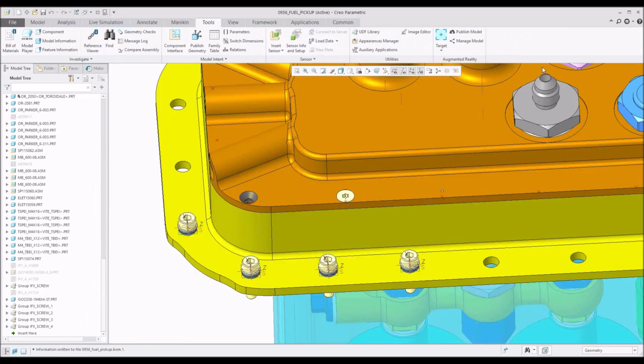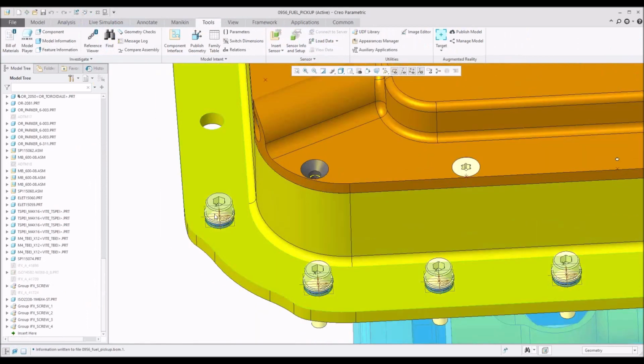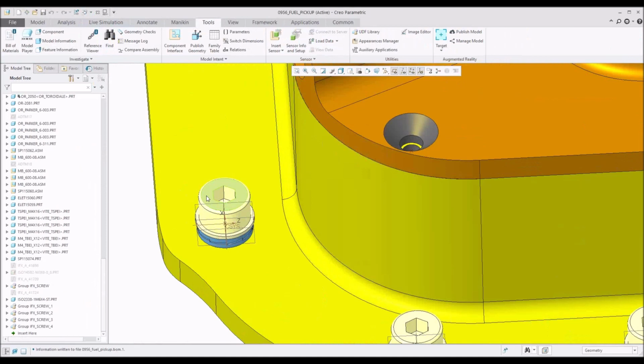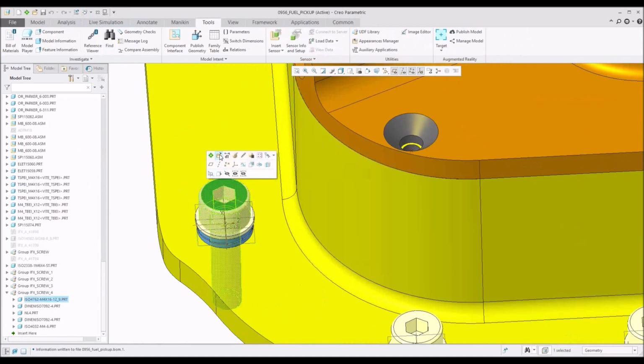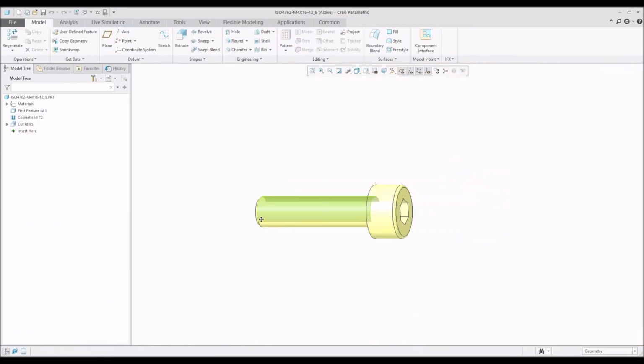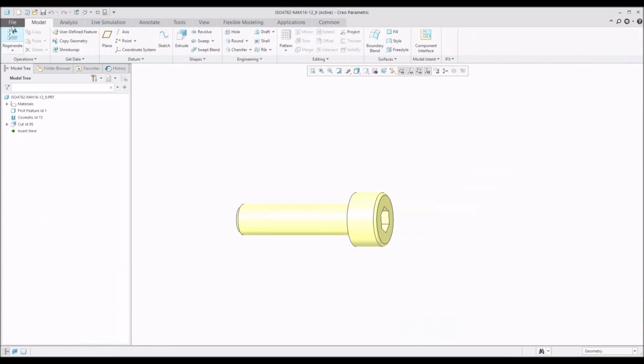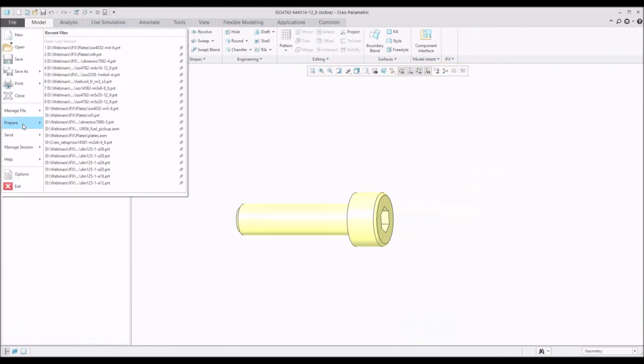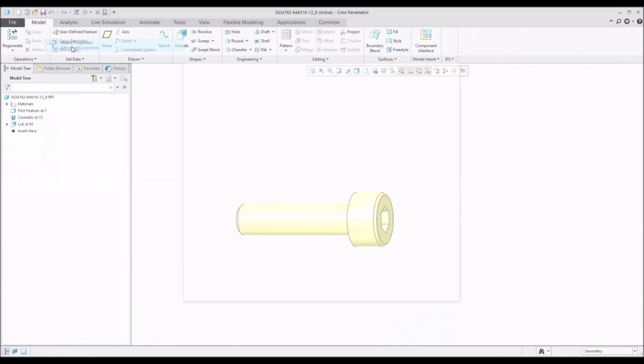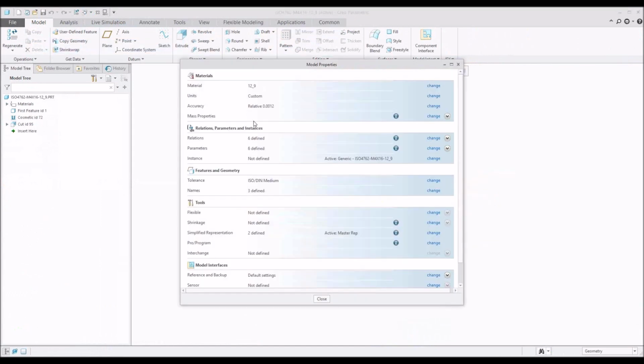That brings me to something else that I forgot to mention, is that these are normal Creo parts. So if you open one of them, you can actually view the mass properties of it. It's not just adding it to the bill of material, it will add to the weight of the assembly as well, because the materials and everything is already added in these start parts.